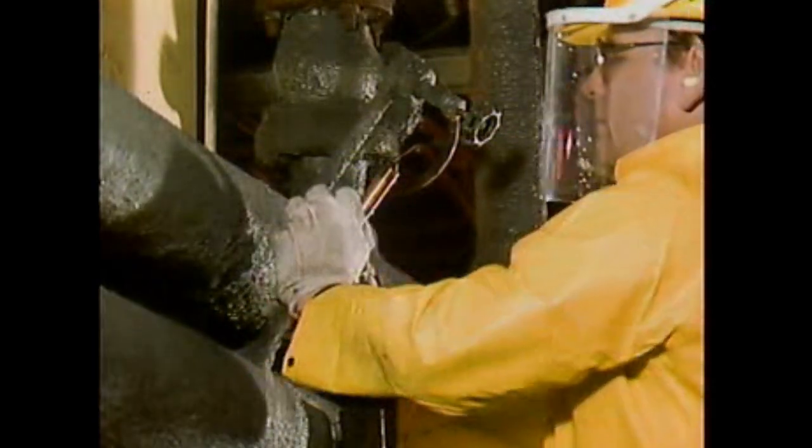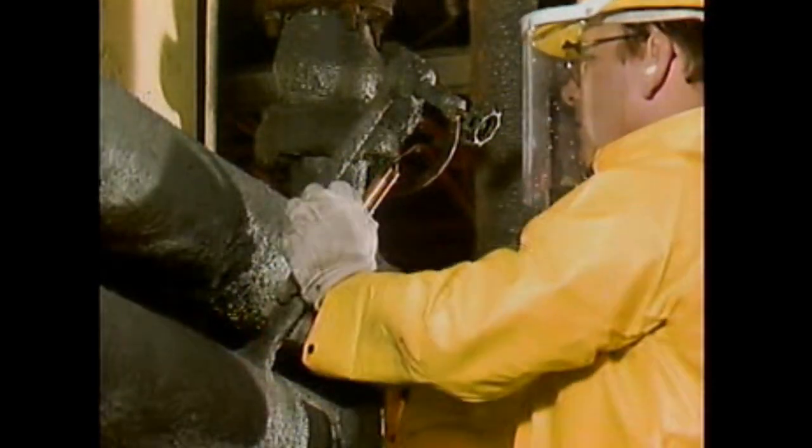This allows air into the piping, which helps any remaining liquid to drain. Draining is generally considered finished when the flow of liquid through the drain stops. However, flow could also stop if the drain line is plugged, so the drain line should be checked to make sure that it's clear. If there's more than one drain line, check the discharge from all of them.